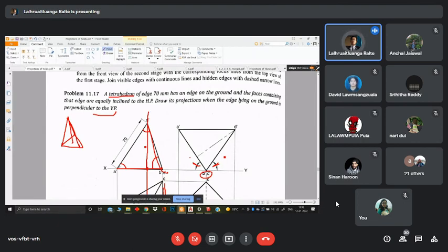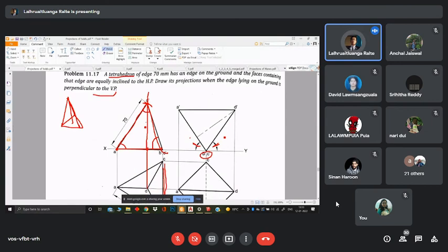And from here, making a circle is a lot easier. We take an arc of 70 mm, and we touch it over here, and that gives us 70 mm. Or you can simply rotate your scale and let it meet where the point 70 mm is, but getting a circle would eventually be a bit more accurate. And then you have that.